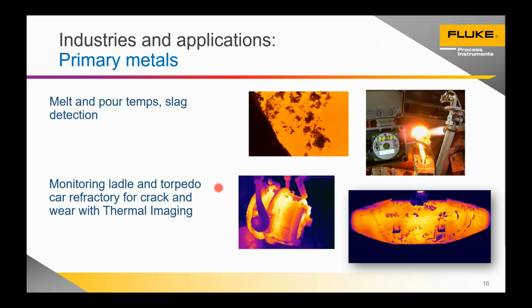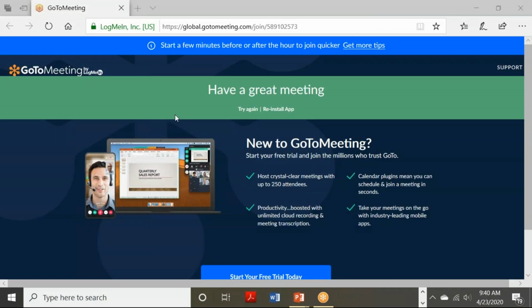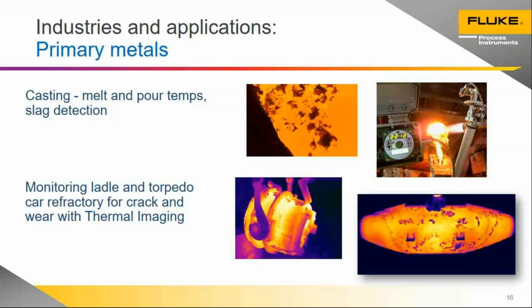Is that similar to the FLIR camera? In a word, yes. All thermal imaging FPA type cameras of that type, so what we're talking about is 8 to 14 micron general purpose. We're all using the same core technology, which tends to be a VOx coated bolometer. The difference between manufacturers are typically either where they get their engines from or whether they make them in-house. And there are some differences physically in designs in terms of optical quality.